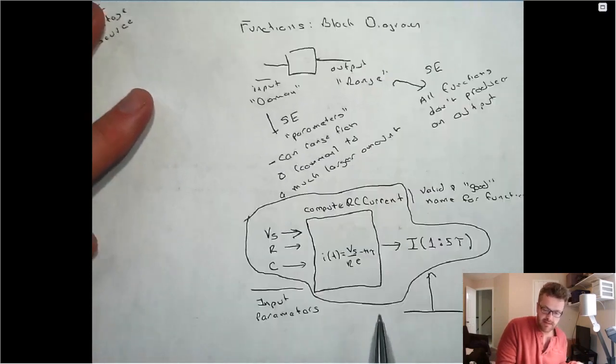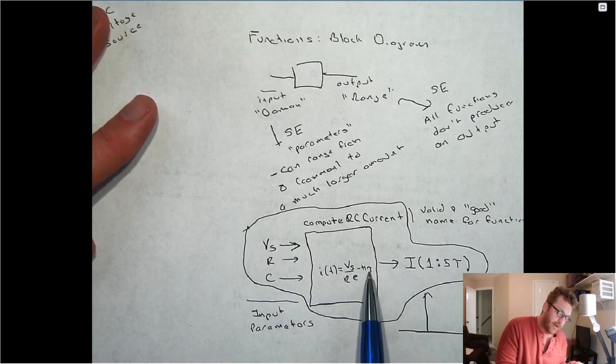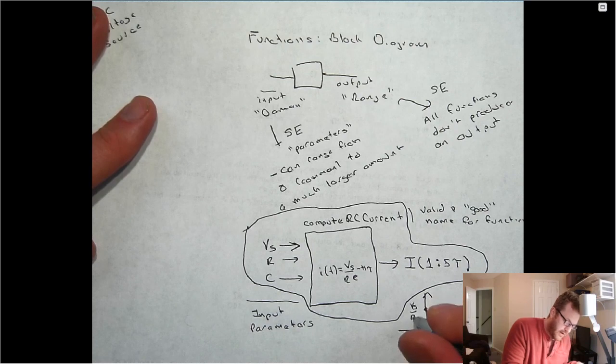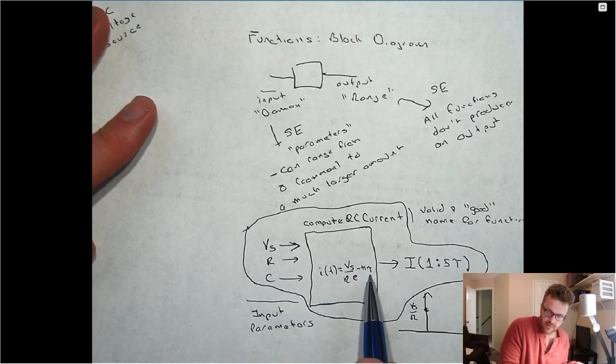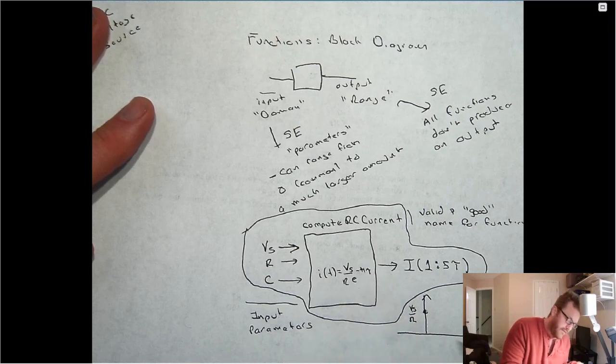And hopefully everyone remembers in this exponential function, regardless of what r and c are, which will determine what tau is, when t equals 0, this becomes e to the 0. E to the 0 is just 1. So this means that at t equals 0, this will take on a peak value of Vs divided by R. And then since tau is always going to be positive, since r and c are positive values, this will just be an exponential decay function.